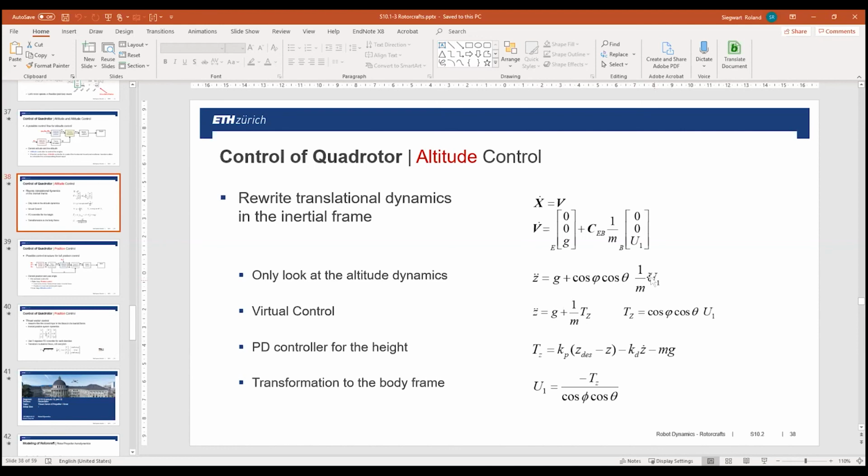I think it's correct, and you can see here that we have the u, which is the control, which is the thrust vector multiplied by these 2 angles. And here is the minus. So the feedback has the minus sign involved, and not the u directly. We have defined more or less the force generated by the thrust as going in the positive direction of our coordinate system. But you could do it also the other way around. So all these signs, you have to define them, and you have to be consistent, and then it will work out.